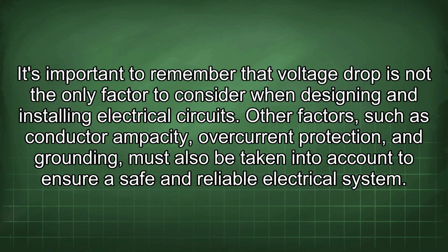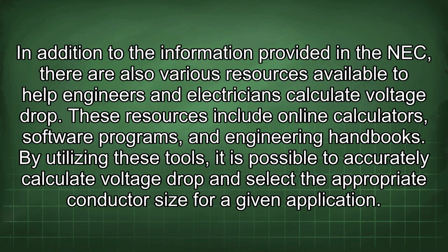It's important to remember that voltage drop is not the only factor to consider when designing and installing electrical circuits. Other factors, such as conductor ampacity, overcurrent protection, and grounding, must also be taken into account to ensure a safe and reliable electrical system. In addition to the information provided in the NEC, there are also various resources available to help engineers and electricians calculate voltage drop. These resources include online calculators, software programs, and engineering handbooks. By utilizing these tools, it is possible to accurately calculate voltage drop and select the appropriate conductor size for a given application.